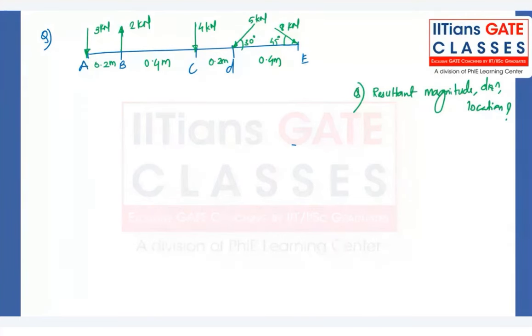Okay, so how many horizontal forces will be here? You can clearly see only these two forces will create a horizontal component, because the rest of the forces are in vertical direction. So summation of all horizontal forces will be minus 5 cos 30 plus 8 cos 45, right?